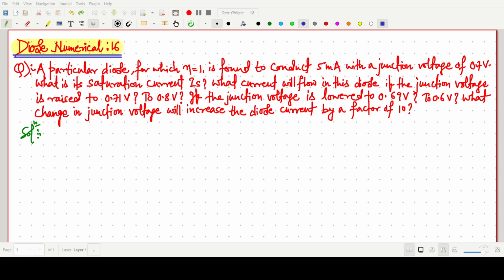Welcome everyone. In this video lecture, we will solve a diode problem which is from the microelectronics circuit book. The question is: a particular diode for which the ideality factor eta is 1. What it means is the eta value is 1 means the diode is made using standard IC fabrication process. It is found to conduct a 5 milliampere current with a junction voltage of 0.7 volts. So we have to find the saturation current Is.